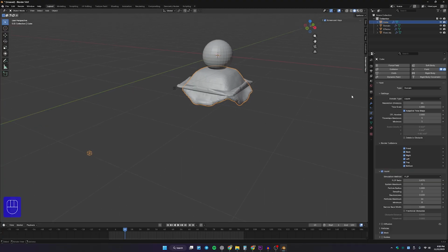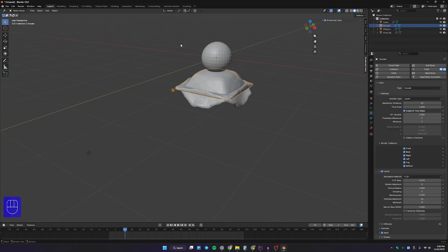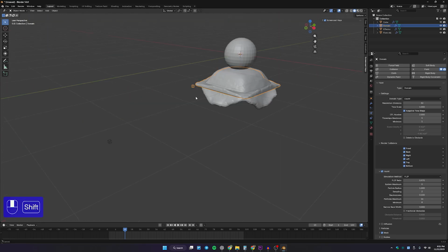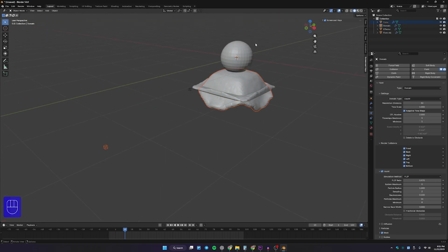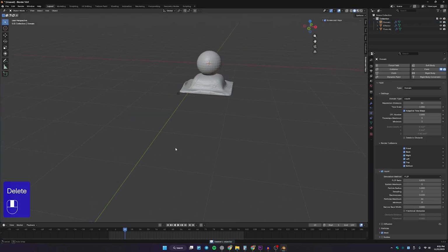You can simply remember that a higher number of resolution divisions means a higher number of calculations. So that's why, if your simulation takes place in a small place, you have to make sure your domain is just fitting that specific location. You should not create a gigantic domain that covers the entire scene. That's a really important point.